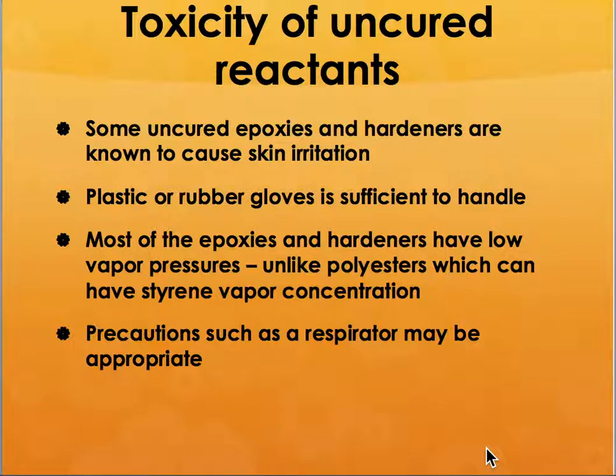Now, there are some precautions that you need to take for those people who are actually on the shop floor handling these chemicals, because some of these uncured reactants are toxic. At the very minimum, they have been known to cause skin irritation. So you have to use plastic or rubber gloves, the right kind of gloves. The other thing to note is that most of the epoxies and hardeners have low vapor pressures, so you have to use some kind of respirator to prevent inhalation of those fumes.